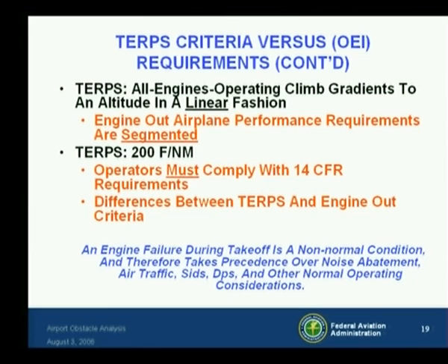TERPS typically assume a climb gradient of 200 feet per nautical mile, unless a greater gradient is specified, but operators must comply with the 14 CFR requirements, 121.189, to account for the differences between TERPS and engine out criteria, including the lateral and vertical obstacle clearance requirements. This, folks, is what we call in the business the numbers.